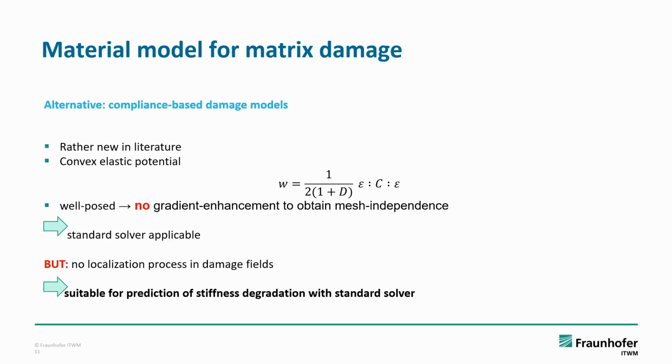The alternative approach that we are trying to follow here is rather new in literature. It's a convex elastic potential, which is damaged by the variable d, which is set in the denominator of the material. And the advantage is that it's well posed. It doesn't need a gradient enhancement, and it's still not mesh dependent. So standard solvers are applicable, but there is no localization process in the damage field to be seen.